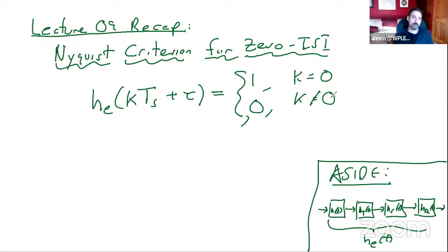Of course, don't forget, we're sending a continuum of data. So if we shift by Ts to the next symbol, we should get its desired value and everything else should be sampled to 0. What this does is eliminate any unwanted contributions that spill over from other symbols, hence the intersymbol interference.